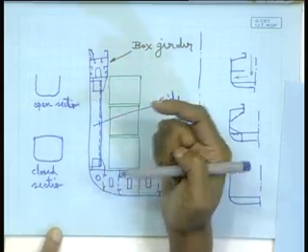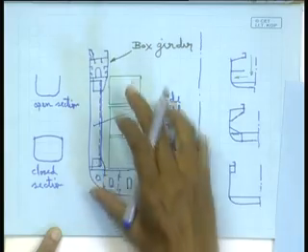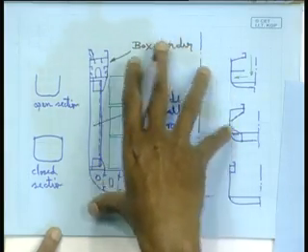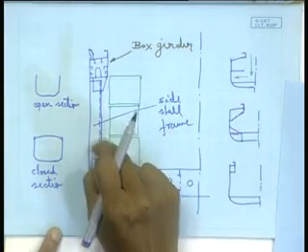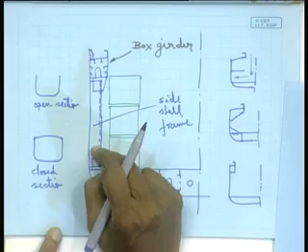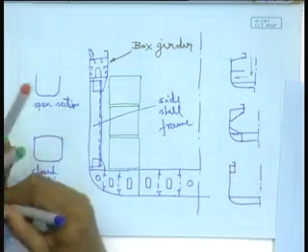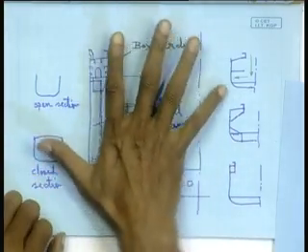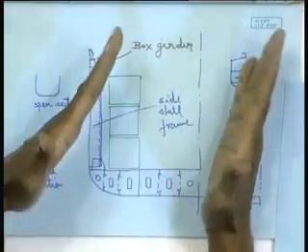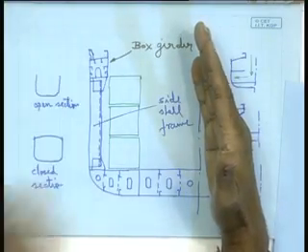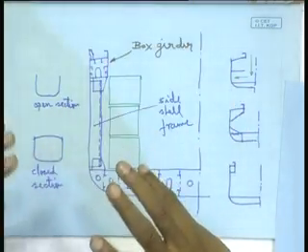Not only that, for torsional strength requirement, this transverse framing is better, because to provide for torsional strength I need transverse strength also. Torsion means it gets twisted. If you do not have transverse strength, it gets deflected in the transverse plane. So, if I provide for transverse strength, it automatically provides for torsional strength.